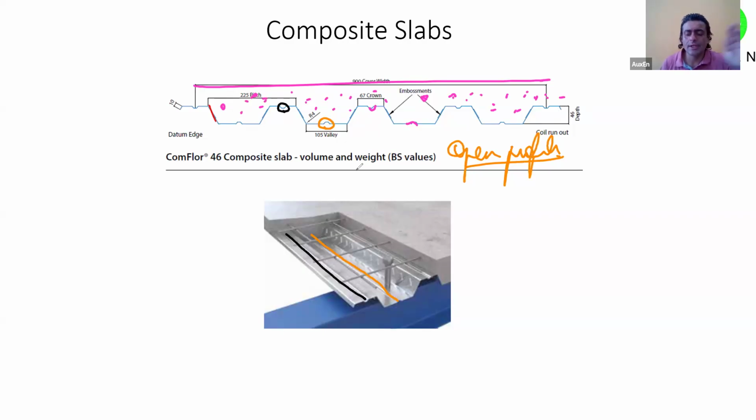Rajenji is saying to increase the Z. Yeah, but this will only very marginally increase Z. This is around 10 mm, not even 10 mm, 2 mm, 3 mm, 5 mm. So it does increase Z, but that is very negligible. Yogita ji is saying better composite action. Correct. In composite slab, we do not provide shear connectors.